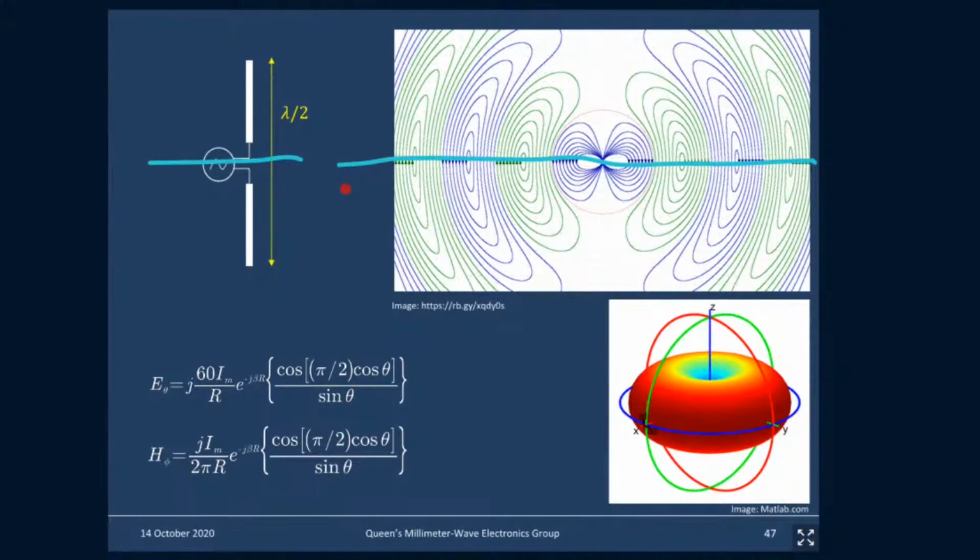From an abstract point of view, we have a virtual ground right there, right down the middle, right? Because this is differentially fed. These two halves of the antenna are differentially fed. So if you actually put a metal plane, a ground plane all the way down the middle, what you end up with is what we know as the monopole, right? A monopole.